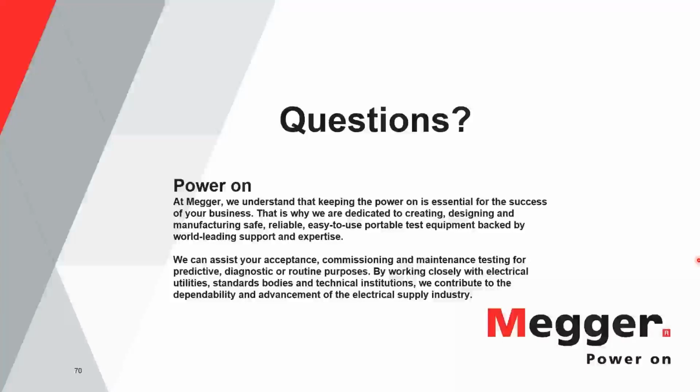And basically, if you're not repeatable on your connections and your measurements, even if you're using just your own kind of grounding method, and then you go through and use that device again and your grounding's not the same, it can vary in those high frequencies.